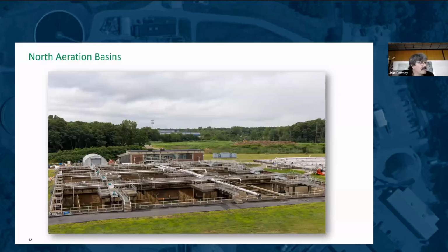It's fortunate we have basin 1 offline. You remember the baffle walls from Adrienne's introduction. They're arrayed throughout these basins. They were installed as part of this upgrade to slow down the velocity and provide some separation of aerated and anoxic zones. Basins 1 and 2, as Adrienne mentioned, are 1.5 million gallons. 3 and 4 hold 1 million each.